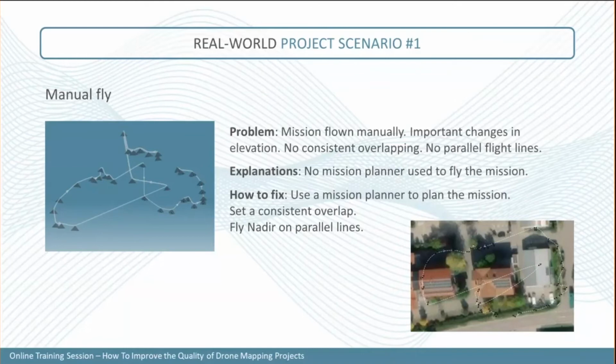If you're looking for mapping purposes, what you can do is use nadir imagery for the DSM, the ortho, and the mosaic creation, and then you can also use oblique imagery, if you want to include it, to texturize your overall 3D mesh.